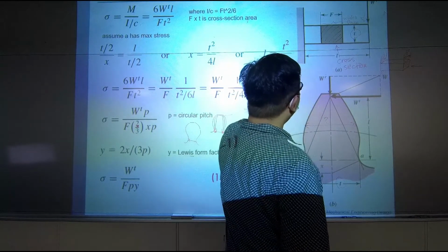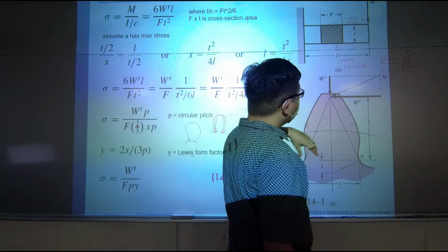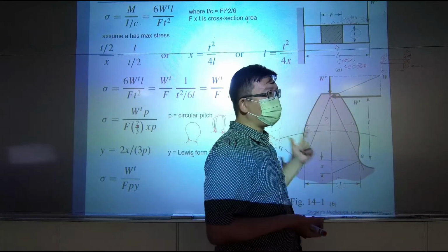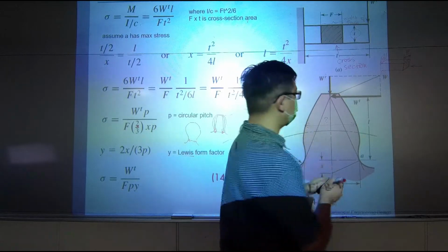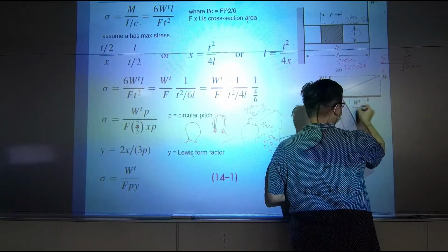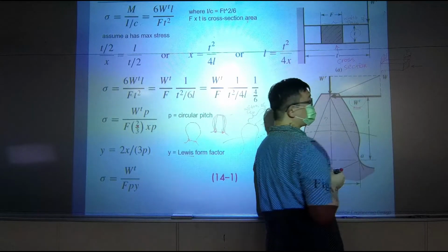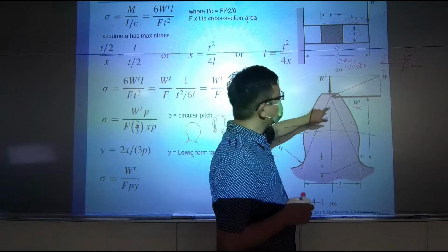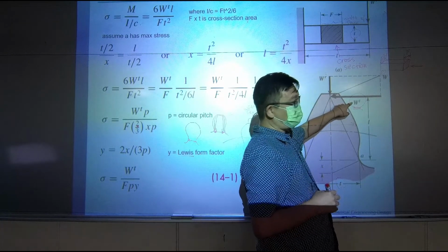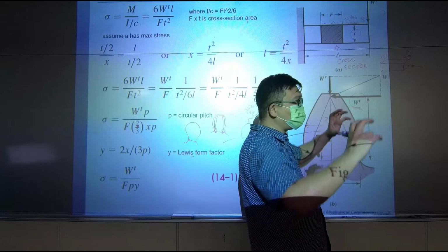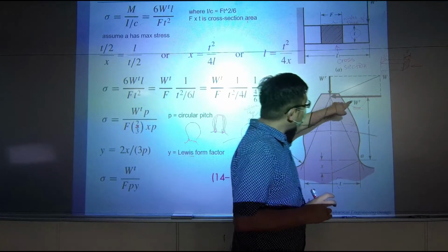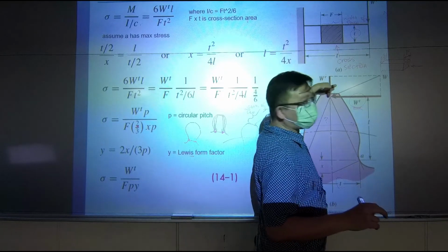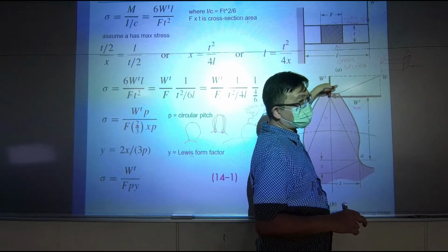And also, previously, why do we need to know how to measure the transverse force? This one. This is the transverse force. Because when we try to analyze how strong the tooth is, we need to know how much load is generating the bending. Only this one is trying to bend this cantilever beam. This one doesn't bend.